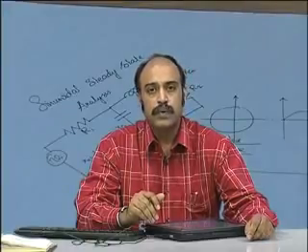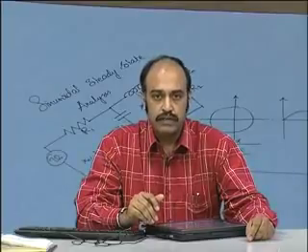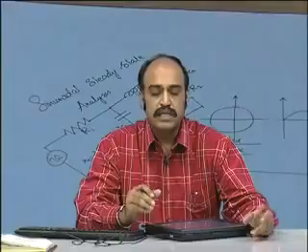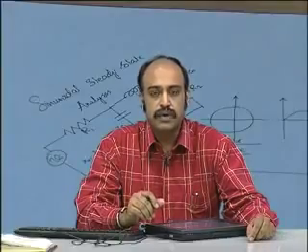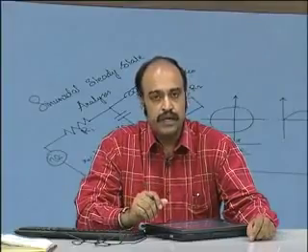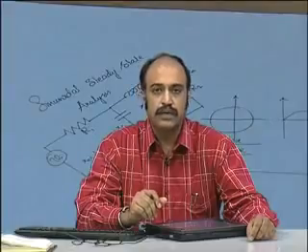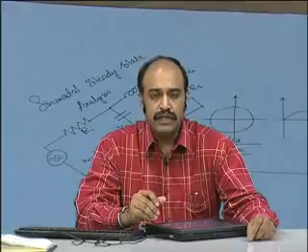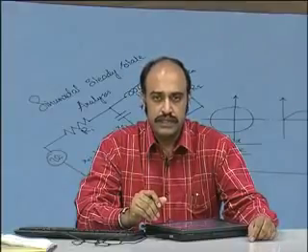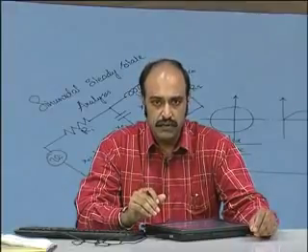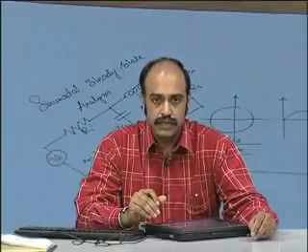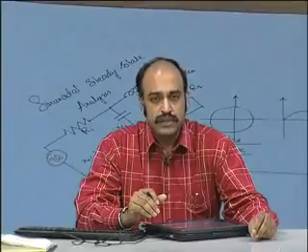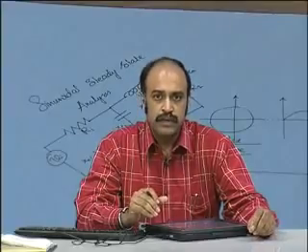That is, we define the state variables of the circuit or the system, which is basically the energy storing variable associated with the energy storing element in the circuit, like the C and the L. And after that we obtain the state equation. The state equation is of a standard form, which is x dot is equal to Ax plus Bu, and the output equation y, which is equal to Cx plus Du.